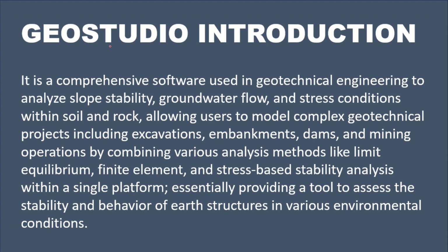So let's have a look at what is basically the SLOPE/W module, or GeoStudio's SLOPE/W module. So basically, yes, GeoStudio is a pretty powerful, comprehensive software. It is being used by most of the geotechnical engineers around the globe, and it is best for analyzing slope stability, for simulating the groundwater flow, stress conditions within soil and rock.